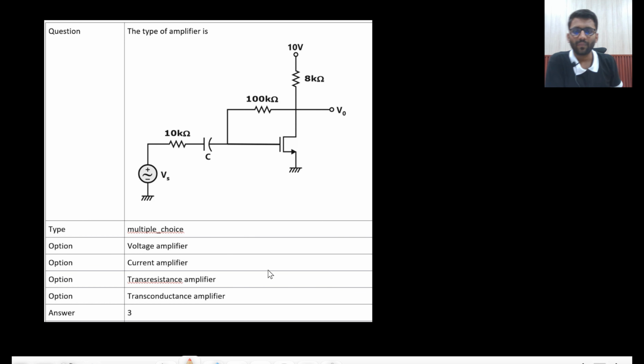Well and good. So what kind of amplifier is that? How will we check? By the sampling and mixing. So current mixing is there, certainly. If this is the current, then it can be divided into two parts. You will not say that sir, input current is 0. It still has two parts, it can be divided. So current mixing is there. And what about sampling? Voltage sampling is there because from the feedback, direct V node is connected. So from here some part of V node can come.